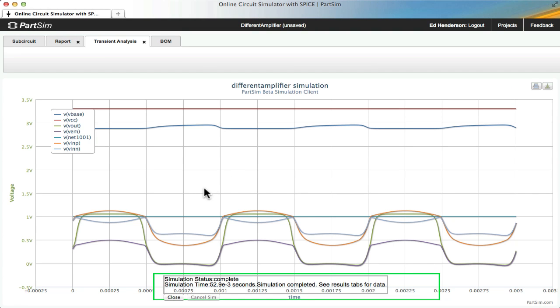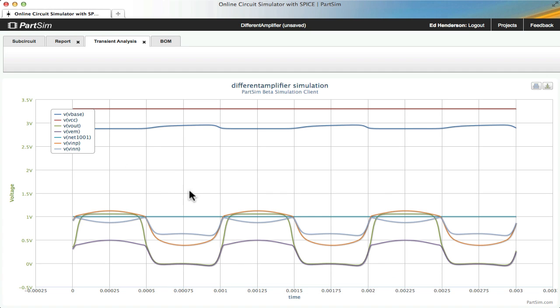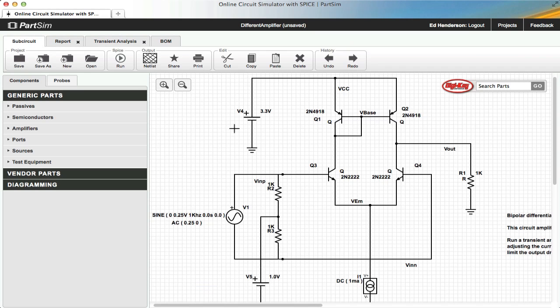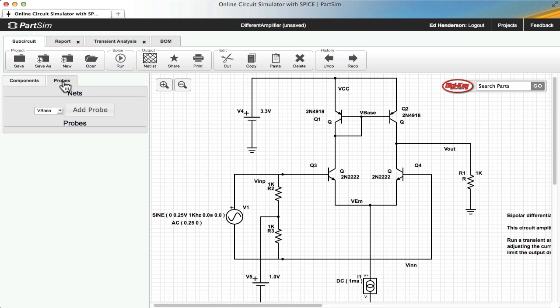then the simulator will attempt to simulate all of the nodes in this circuit. Now that can be quite busy and sometimes just contains too much information. So I can use the Probes tab, which enables probes mode and allows me to probe certain nets. So I can probe the VNP, VNN, and Vout nets, which now adds 3 probes to my list.